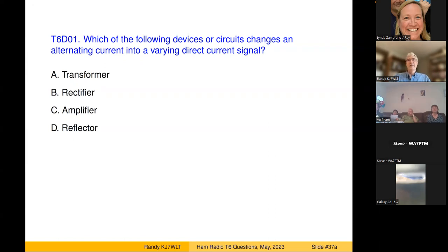But then if you want to plug your 12 volt radio into that in order to power your radio, you not only have to convert 110 volts into 12 volts, you also have to convert that alternating current into direct current that's only flowing in one direction along a wire. So if you want to take an alternating current and turn it into sort of a one-way current, then there's a particular electrical component we've talked about that only allows current to flow in one direction. And so that's kind of a building block often of this sort of device that can turn an alternating current into a one-way current, because it can just let the current go in one direction and block the current when it's flowing in the other direction.